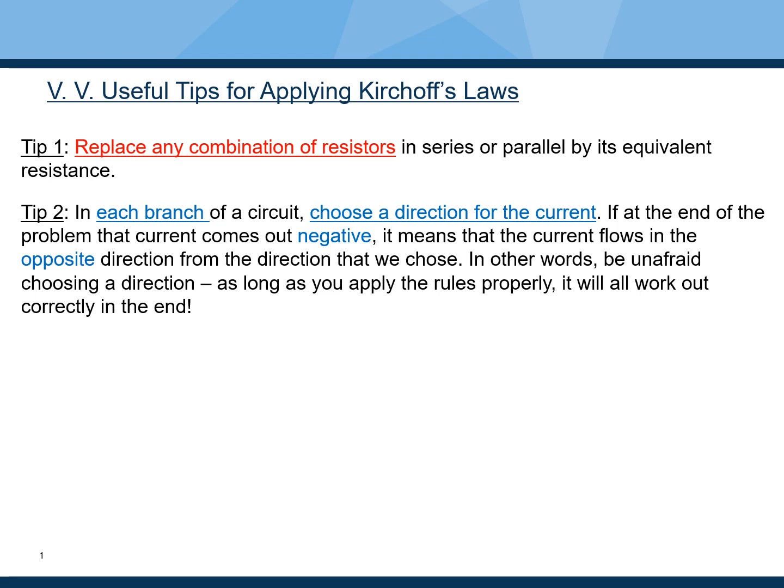What I'd like to do is begin with the 7 tips that we set up at the end of the previous unit, and we'll go through it really fast. Tip number 1, replace any combination of resistors in series and parallel by its equivalent resistance. Tip number 2, don't be afraid. Go ahead, draw some direction for the current.